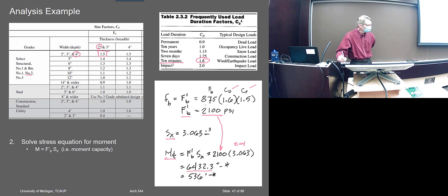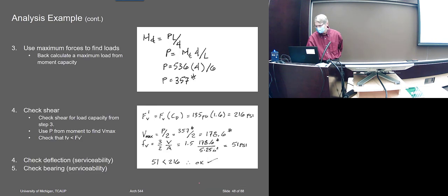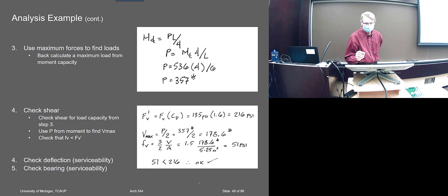I'm going to divide that by 12 to bring it down to foot pounds, 536, so the moment is 536 foot pounds.